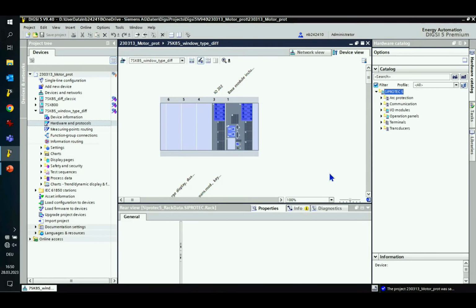And now this overcurrent protection function I can set for this differential protection function. How to set that stage, maybe a word: in the same range of sensitivity as the classical differential protection, so at a relatively low value. You can test this also during the motor startup.